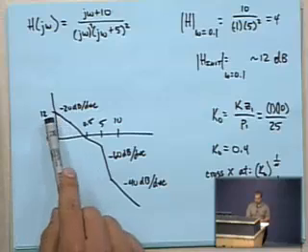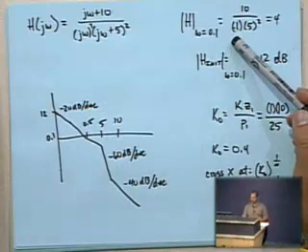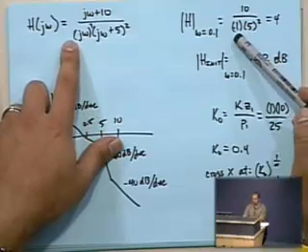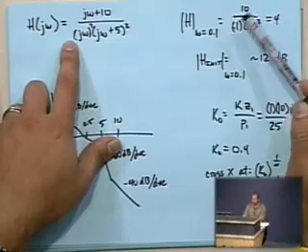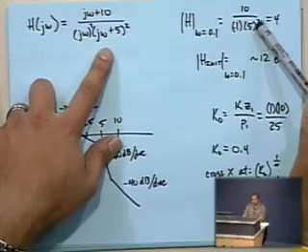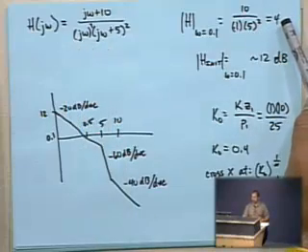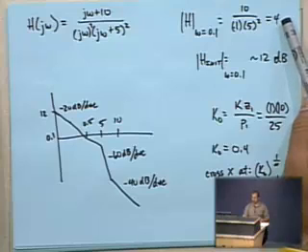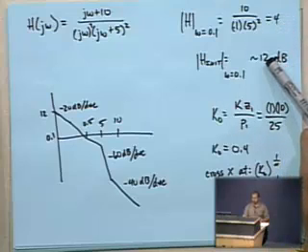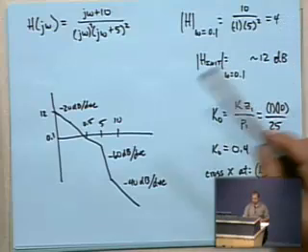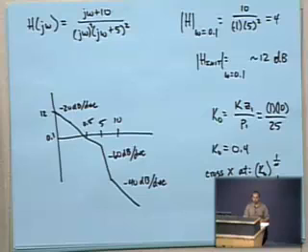The original magnitude we solved for by evaluating our transfer function at 0.1. So you have 10 over 0.1 times 5 squared. And so in decibels, that magnitude 4 is 20 times log base 10 of 4, approximately 12 dB. So that gives us where it crosses over there on the left-hand side. We found approximately where it crosses the x-axis.